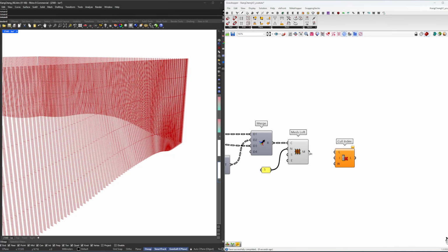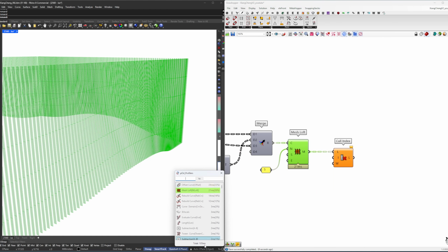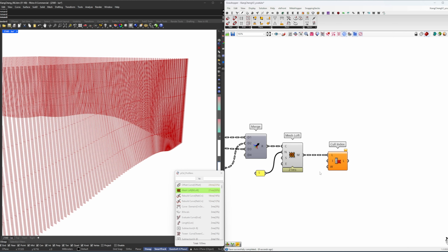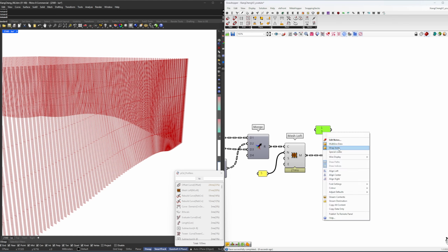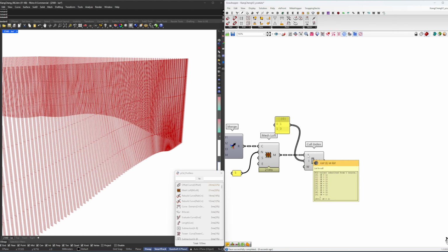Like we said, a few panels we can hide. Also, by the way, we're using a mesh operation because in terms of computational time, we're at 100 milliseconds, which is absolutely nothing for a Grasshopper script. By my head, I think it is 1 and 3 that we can cull. Cull means that we're gonna get something away. And it's not really doing that.